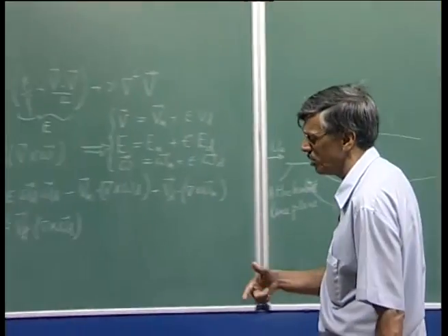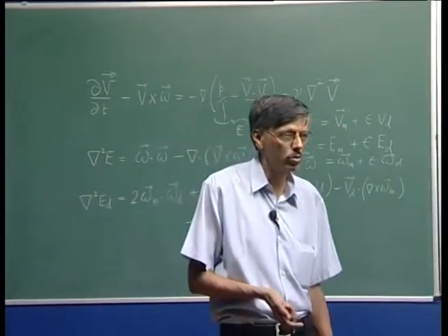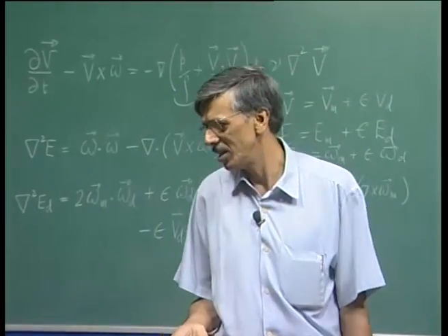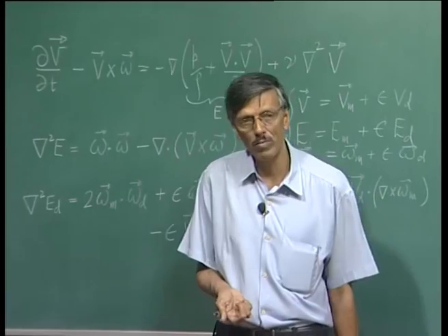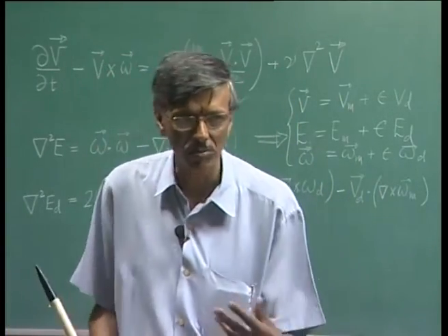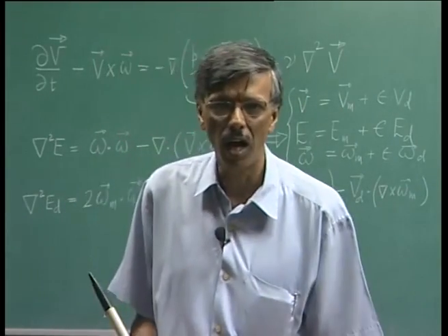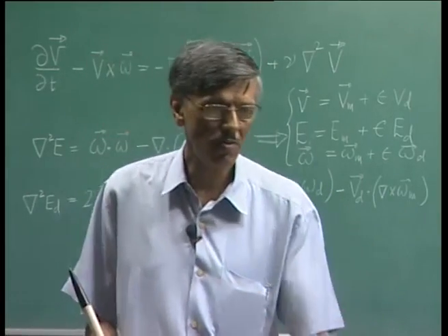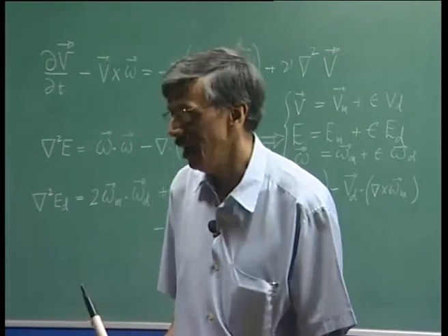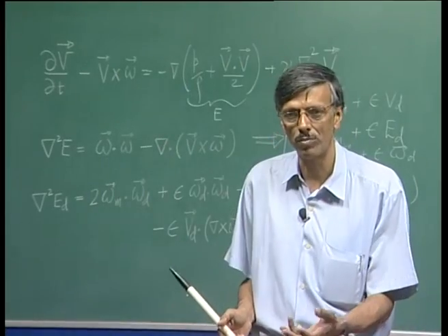This we will find out when we come to the next module of the course, where we talk about non-normal modes, spatio-temporal growth of disturbances. You will realize that for the last couple of decades, people have been talking about newer mechanisms of instabilities. Unfortunately, those kinds of mechanisms are very much biased in favor of the three-dimensional flow field, and they do not work for a two-dimensional flow field.